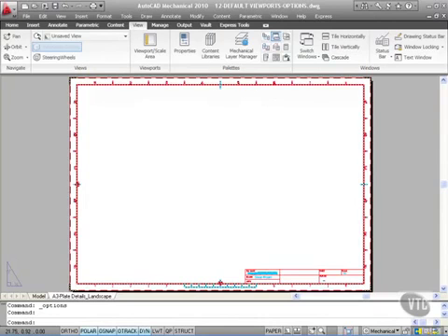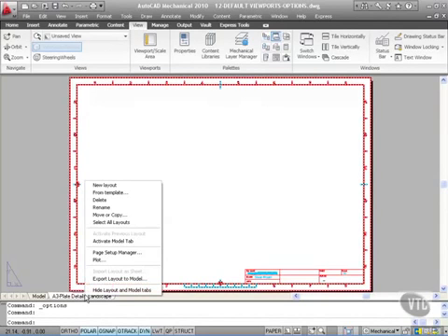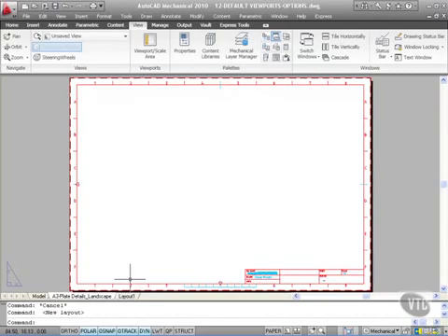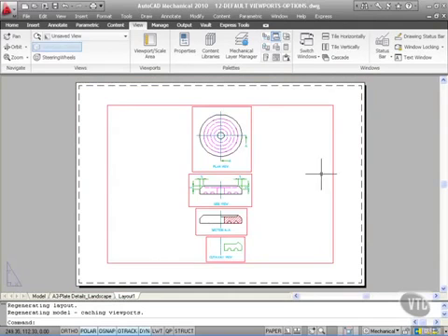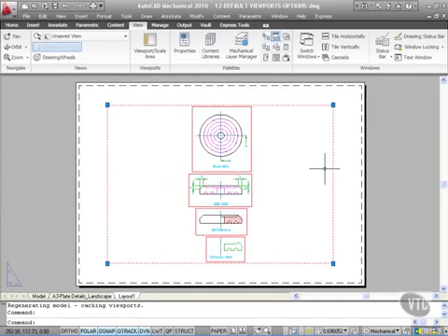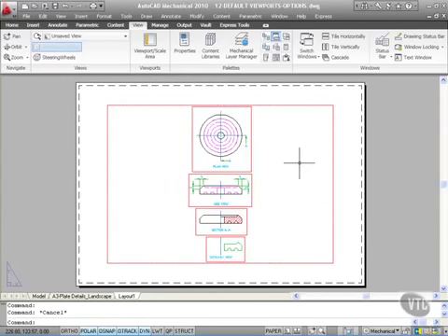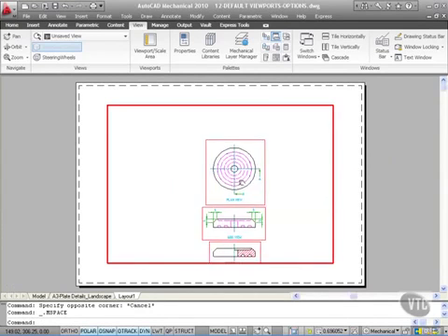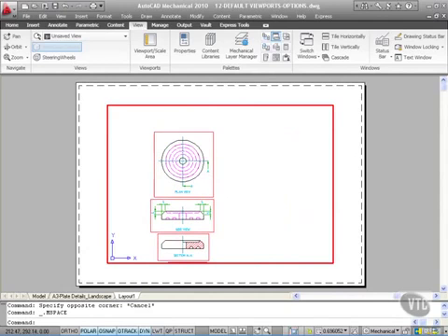Now, right click on the A3 layout tab there, new layout, there's Layout 1, and you'll see now, look, there's a default viewport on the current drafting layer, like so. So if I click on that viewport, or more importantly, double click inside that viewport, I can pan, I can zoom, and so on. So I can have a default viewport if I want one.